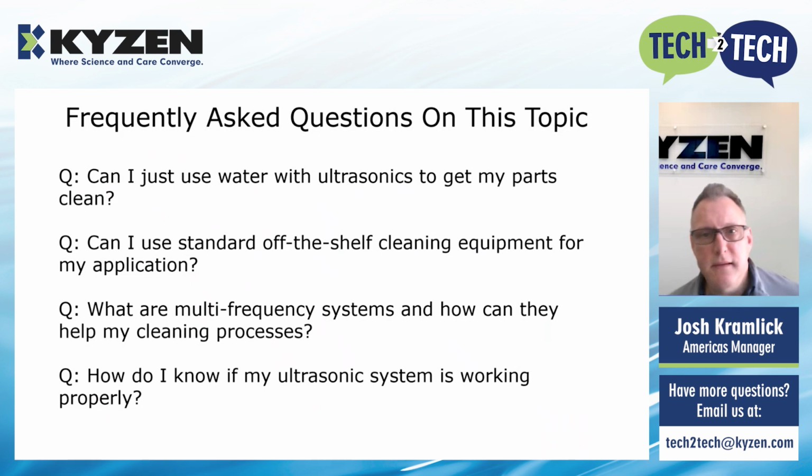What are multi-frequency systems and how can they work to help my cleaning processes? So multi-frequency systems can be developed in one of two ways. One, you can have multi-frequency transducer systems, which are selectable, for example, between 40, 80, or 120 kilohertz. Or you can actually have tanks that have single frequency transducers of different center frequencies mounted on different surfaces. For example, 40 kilohertz on the bottom, 80 kilohertz on the sides, and then maybe even 120 kilohertz on the short sides of a tank. These can all help you tailor a process around the substrates that you're managing and the level of contamination that you're working with.